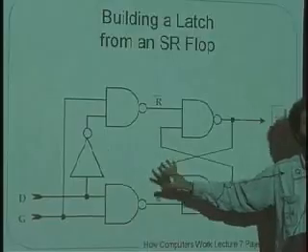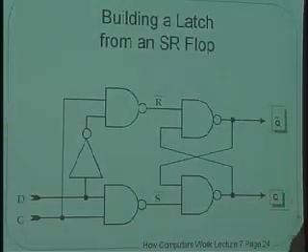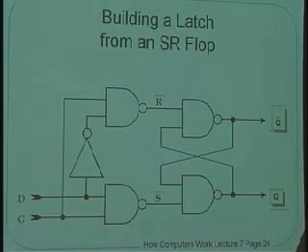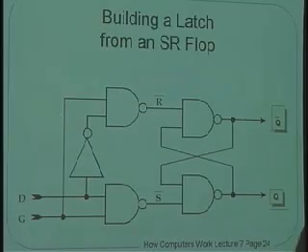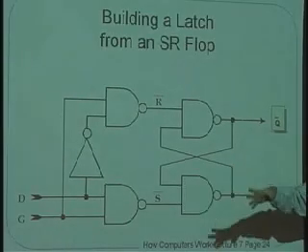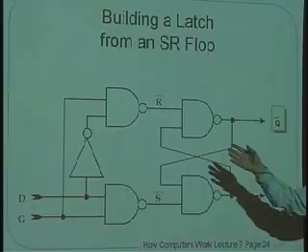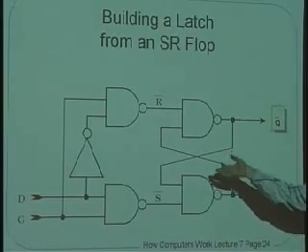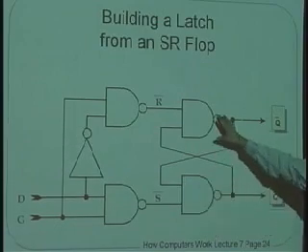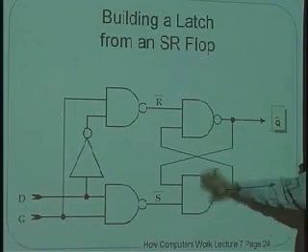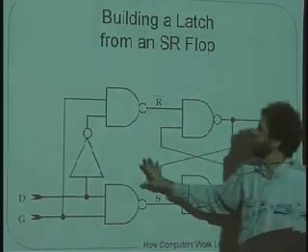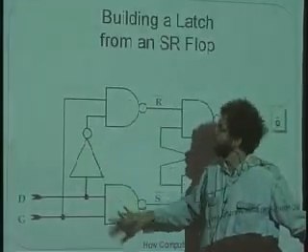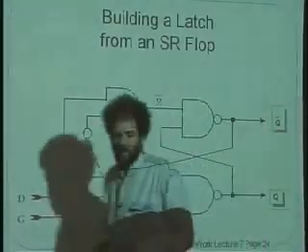This is only done to show you that really there's only one single-bit fundamental mode machine out there, and you can always transform the inputs from one to the other. I can translate a D latch, a transparent latch, into a SR flop and vice versa. This is a way of changing a SR flip-flop, which has a circuit that looks like this, into a D latch by putting some AND gates and inverter on the input. Nice way to think about this.